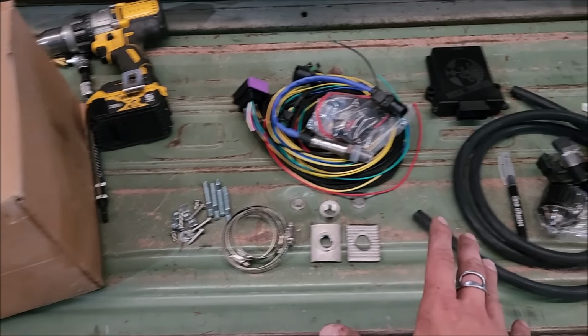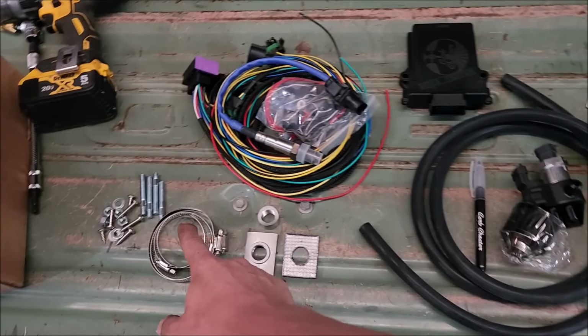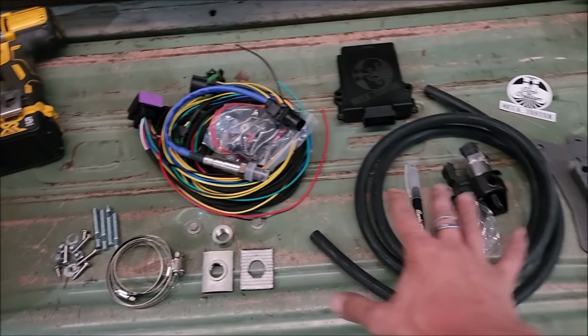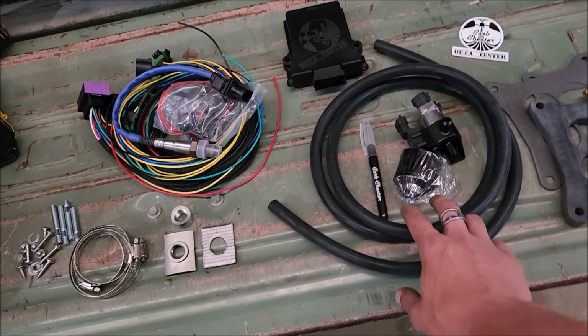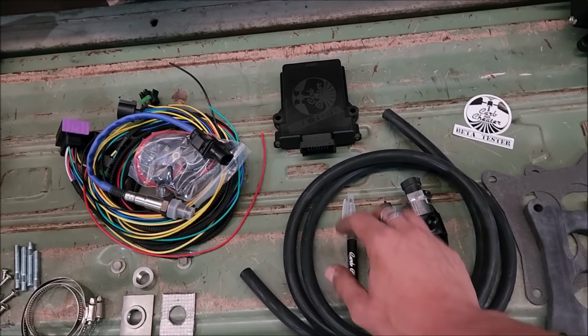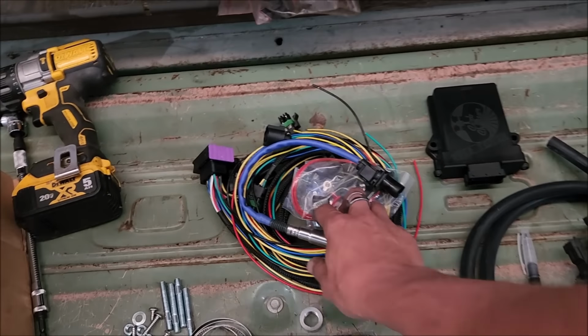But all that aside, here's what comes in the kit: the spacer, gaskets, obviously. As far as the spacer goes, it comes with the hardware, the extended studs to accommodate the spacer, your valve, your map sensor, all that good stuff, the filter for it, some vacuum line, obviously your Carb Cheater module box, your full harness kit with your wideband. You have a weld-in bung or a clamp-on bung, and we'll see why we included this on this truck. The exhaust is really rusty, and we would definitely never get the weld-on bung to cooperate, so we'll see that for the O2.